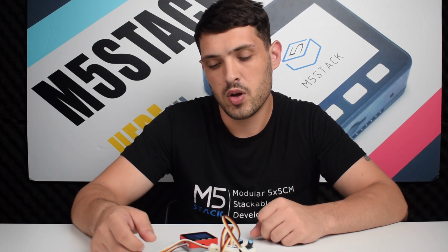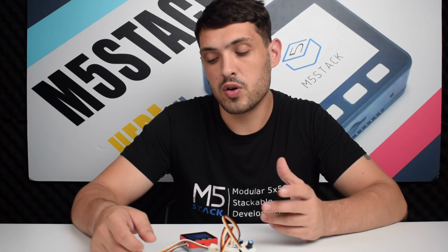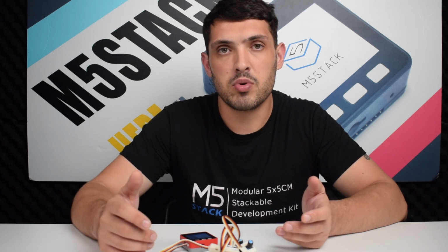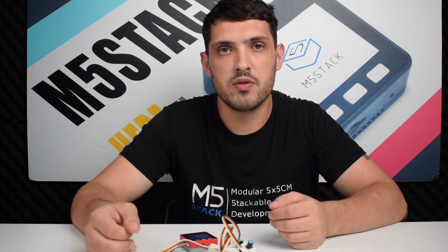So previously we looked at the PAhub, which is an I2C expander for I2C devices. The PBhub also goes in the port A, the I2C port, but it's designed for digital and analog inputs, standard GPIO devices.